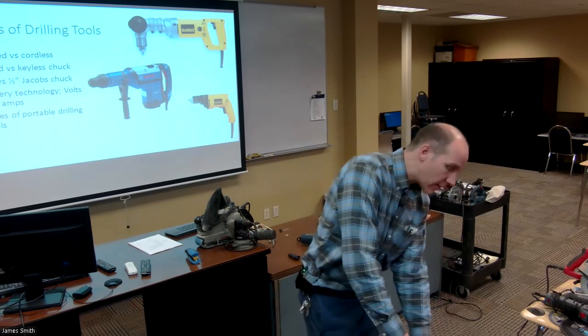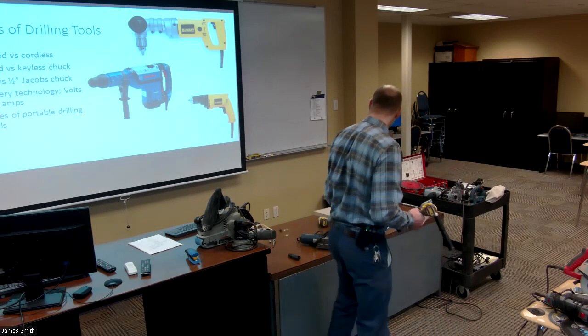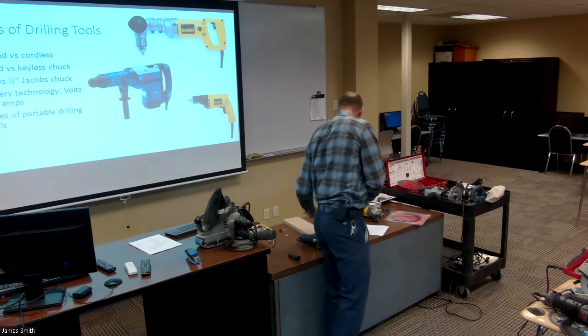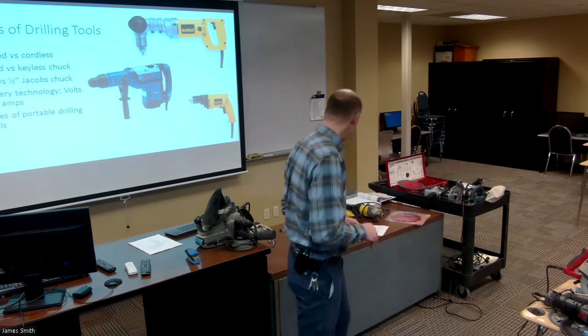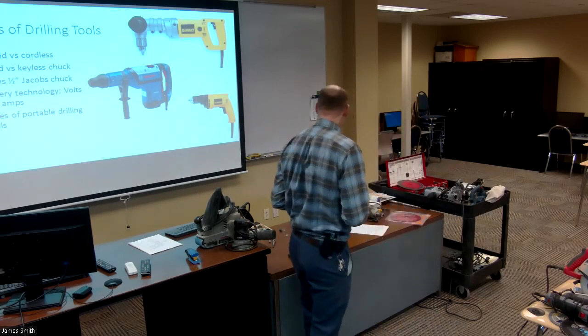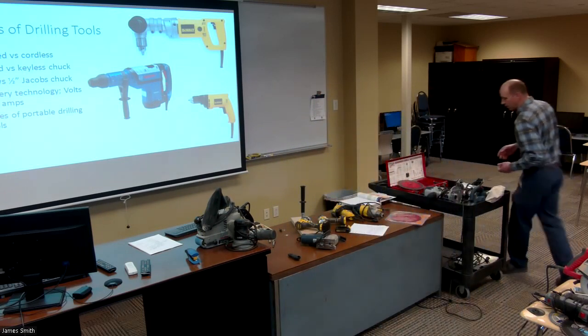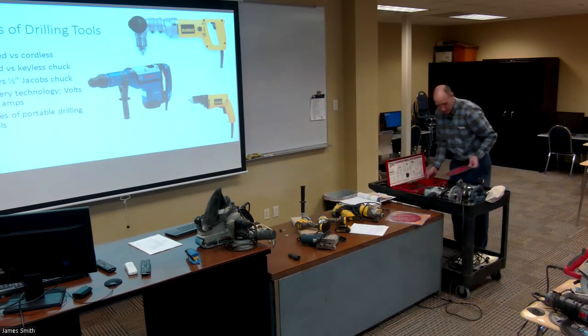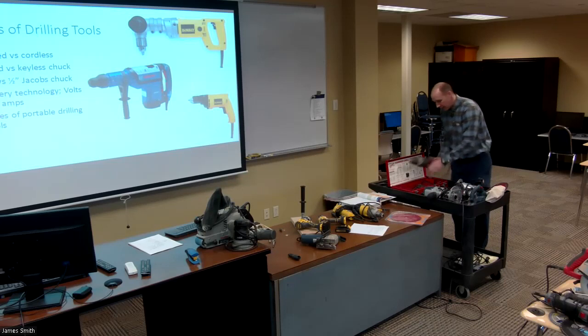you're drilling into concrete, you can hammer. That hammering action helps to break up the cement and the lime and all that, the concrete. So that's really nice. It used to be that, and this is still kind of my preferred tool, if you're doing a lot of hammer drilling, you can buy a heavier duty hammer drill like this, and you can outfit it.